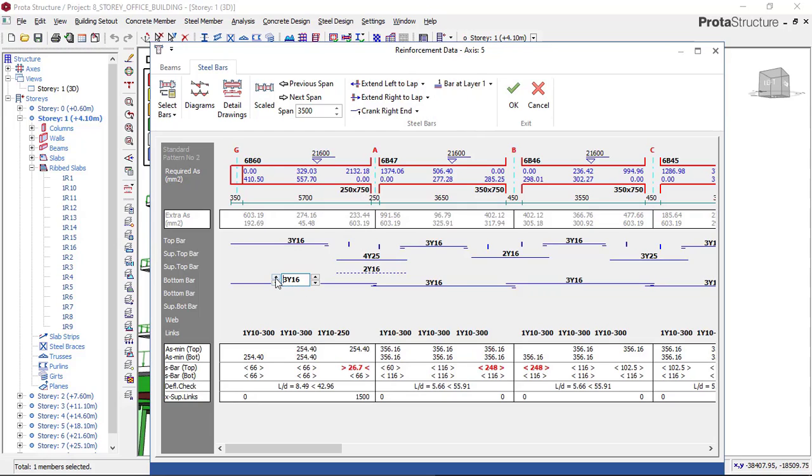So right now go here and increase this to at least 4, because the reason why I increased it was because this was 45. I can see it here, that area of reinforcement here was 45, and I always say that you should at least use up to 75. So since it's showing 45, I will add the number of reinforcement to be 4, which now should be 246.54 millimeter square. So that's okay for me.